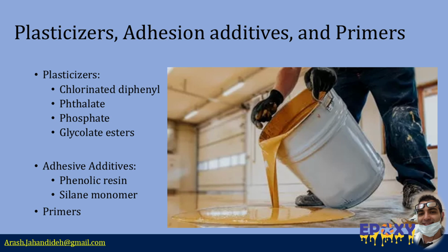Adhesion additives are critical for ensuring that the sealant bonds effectively to the substrate. In two-part building sealants, selected phenolic resins such as Methylon AP108 from General Electric have proven particularly effective in promoting durable adhesion.